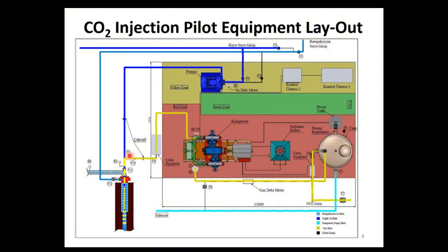And then it comes to the wellhead, and in a parallel way there's a normal, conventional small fresh water well, which is supposed to be a little bit cool. The coolness is important when you motivate this relatively small volume, let's say maximum 10 cubic meters per hour of water. This motivating fluid is the one that vacuums the gas inside, with the Bernoulli equation as the main logic. It's an ejector. The faster you pump this motivating fluid, I mean the water, the more gas you can vacuum and absorb at low pressure.